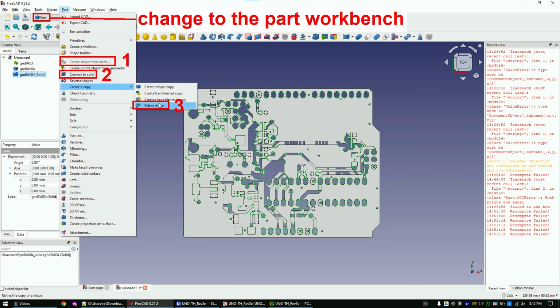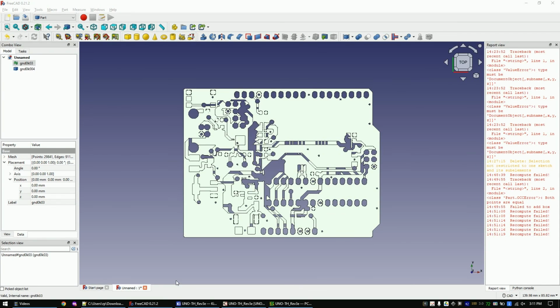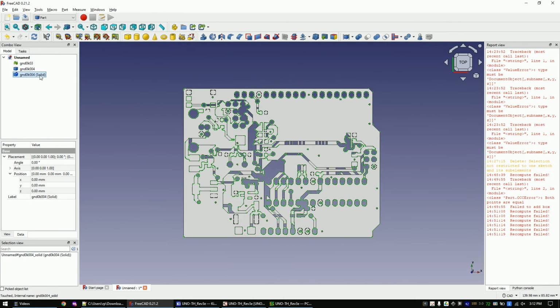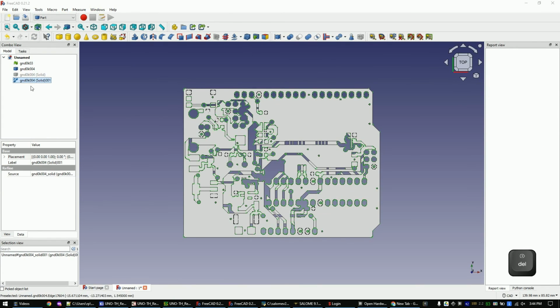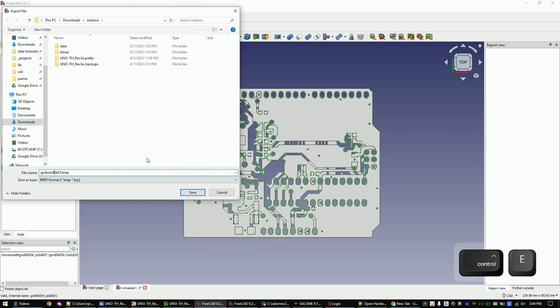Now perform these 3 steps. Save the refined shape as brep file. I chose brep as it is the fastest file format for meshing. Anyway, all the other major file formats would also work.